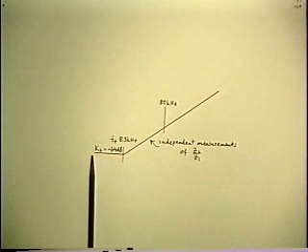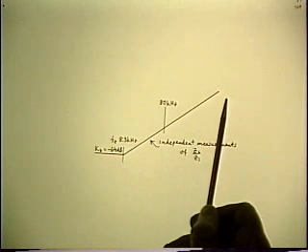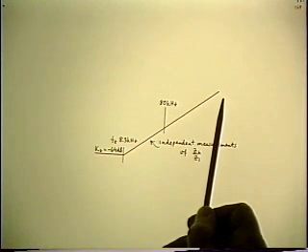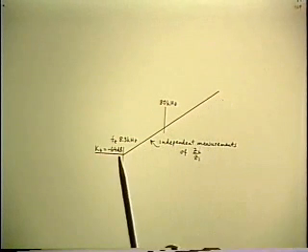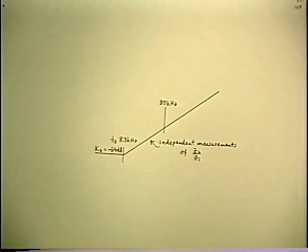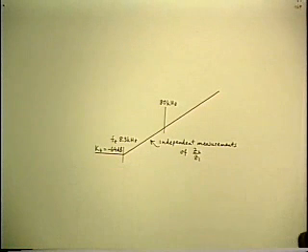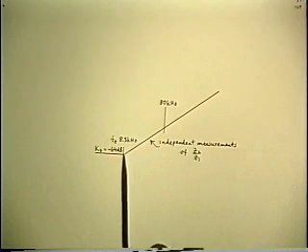Z2 over Z1 is a small number, K sub Z, minus 64 dB. That's less than 1 over 1,000. But it comes up at higher frequencies. Not because Z1 goes down, but because Z2 goes up. In other words, the output impedance of the op amp rises at higher frequencies. In fact, it looks inductive. Again, an example of where you get the property of an inductance, and there's no real inductance there. But it's to do with the internal structure of the op amp. It behaves inductively.